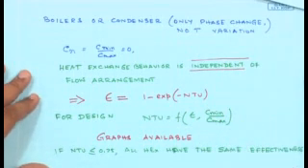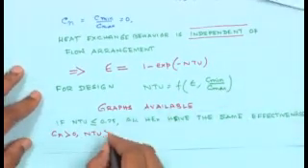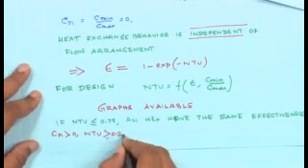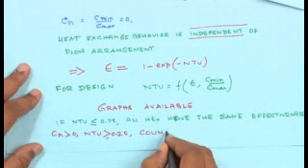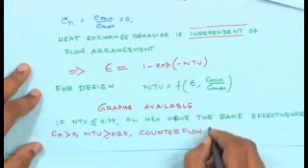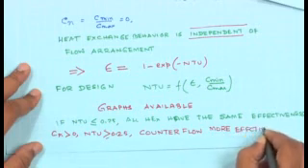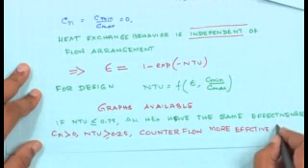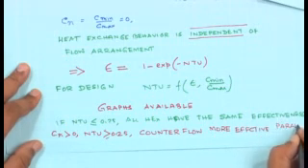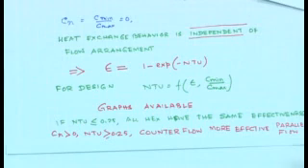Okay. And it is also shown that for CR greater than 0, NTU greater than 0.25, counter flow is definitely more effective than compared to parallel flow. So these are some of the observations which you can make when you look at this heat exchange curve.